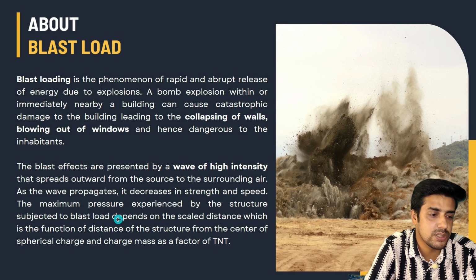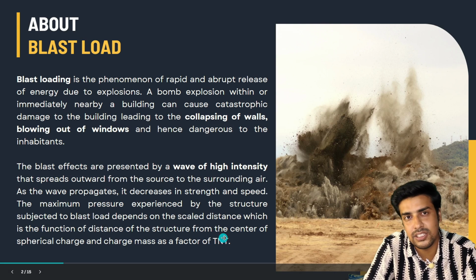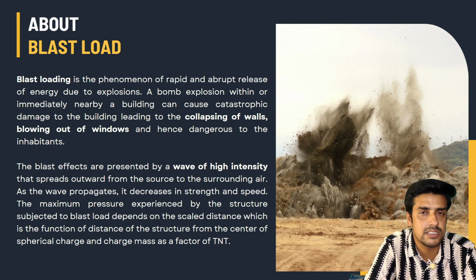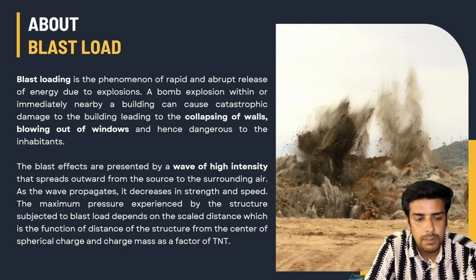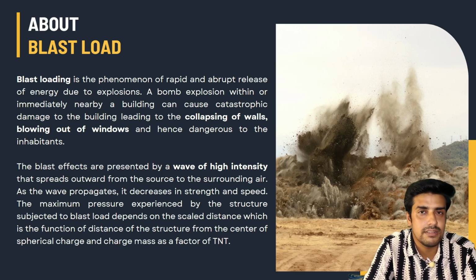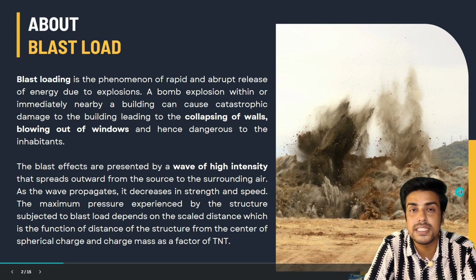So the blast load is dependent on the selected distance. This scaled distance is very important: how much distance you are considering, how far you are from that particular center point. Generally we use TNT as the equivalent of the explosive. Whatever explosive we are considering, we take it as an equivalent of TNT, because there are formulas and charts related to TNT, so it makes our calculation much easier to convert all the impact loads into the equivalent of TNT. Let's move ahead. So this was the basics of blast load.